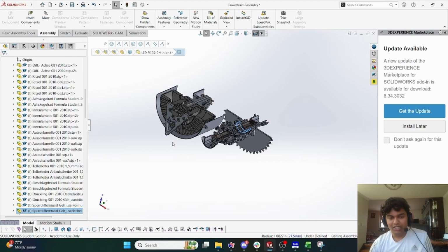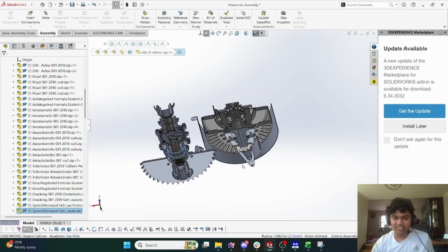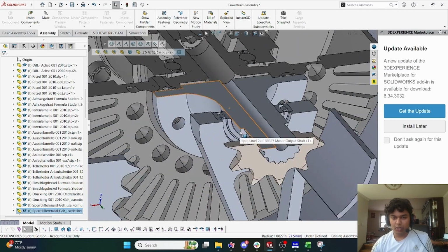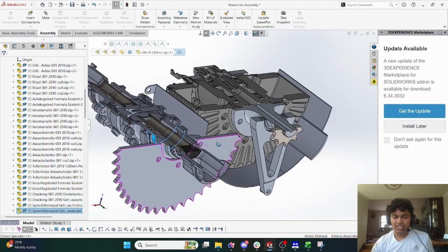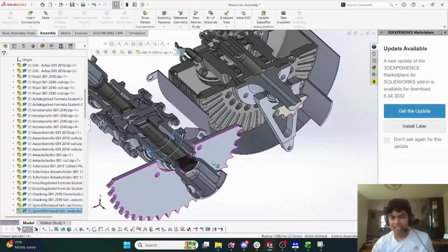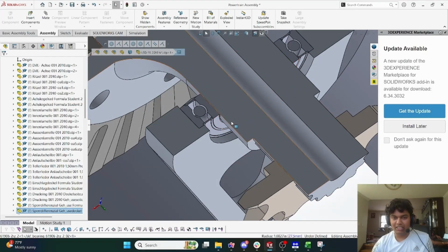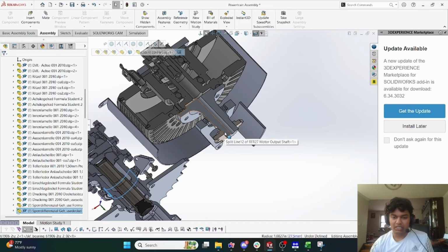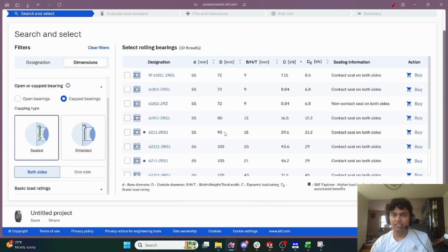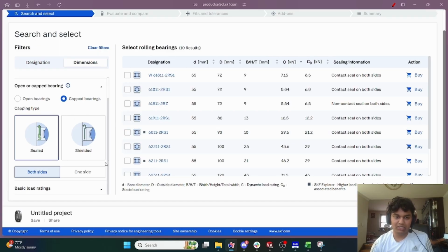You have like an arrow thing at the bottom which helps protect against some of the grime. But the environment is not the epitome of cleanliness. This isn't the lab environment. So we don't want any grime buildup inside of our bearings because replacing our bearings is a very big pain. Sometimes, like for this bearing, we might be required to remake the entire output shaft just to get that bearing in. So it's not realistic to say, just get something that's not sealed and replace it later. For us, making it sealed makes the most sense.